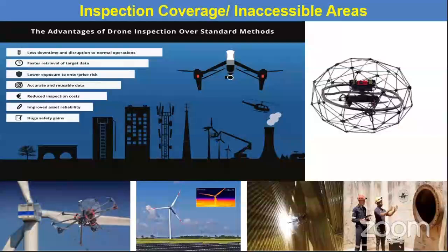A different delivery mechanism is all about drones. And that again is catching the interest of the entire NDE community and inspection community, just because of the tremendous advantage. Just like robots give you an advantage where they can crawl over large surfaces, gather data, and go into confined spaces where human beings need not enter, exactly the same. A drone is something which you can fly to tall structures and large surface areas, and make use of the benefits it can provide in acquiring inspection data at a very fast pace.